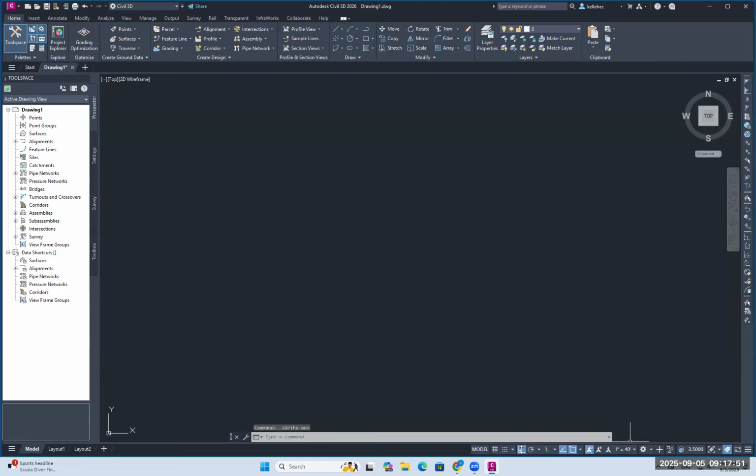If you click on that, you're turning on ortho mode, and you see it down here. You turn it off to get rid of ortho mode. Civil 3D is really interesting in that you can run commands from the command line, or you can run commands by clicking on it, which I think is really helpful. So if you're somebody who really likes visual things, you've got this whole interactive system up here, but you could do the same things from the command line.